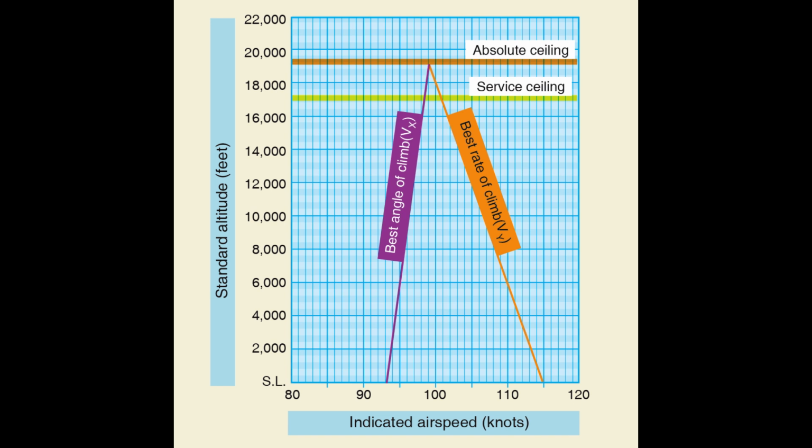As the airspeed decreases during the climb's establishment, the airplane's pitch attitude tends to lower unless the pilot increases the elevator flight control pressure. Nose-up elevator trim should be used so that the pitch attitude can be maintained without the pilot holding back elevator pressure. Throughout the climb, since the power should be fixed at the climb power setting, airspeed is controlled by the use of elevator pressure. The pitch attitude to the natural horizon determines if the pitch attitude is correct and should be cross-checked to the flight instruments to verify climb performance. Figure 3.21, Climb indications.